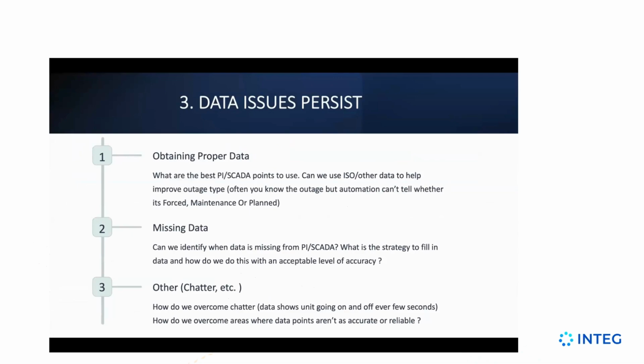To do that, you pick a duration and say, okay, if it goes on and off within seconds more than 2 times, then that's chatter. Then we go back to the first time it started, assume the value before that was the right state, and then we ignore it until we see it stop.